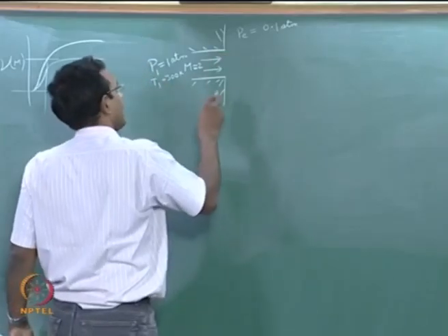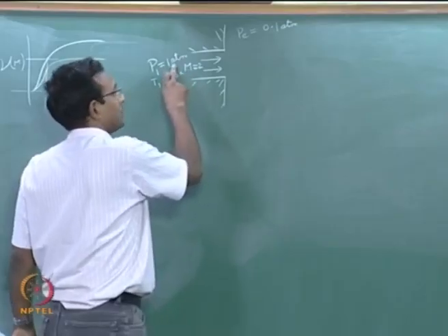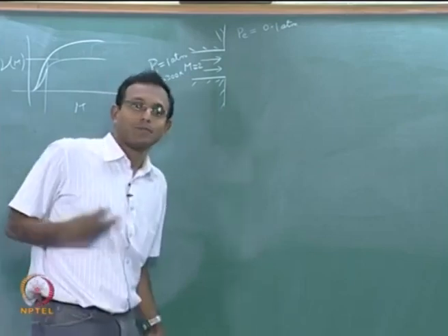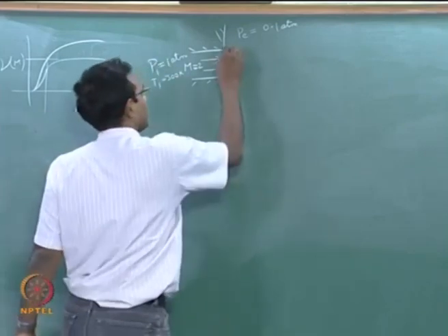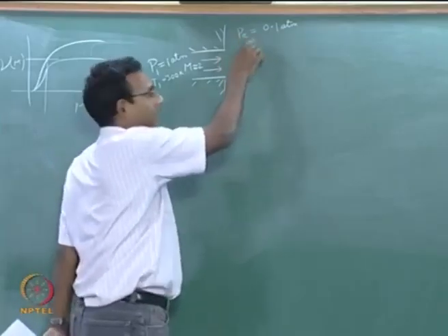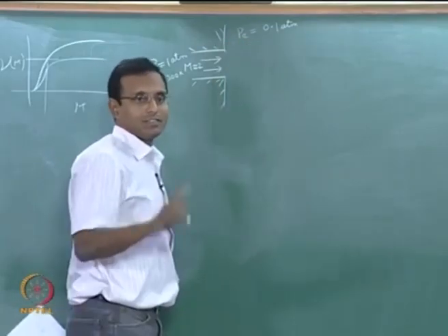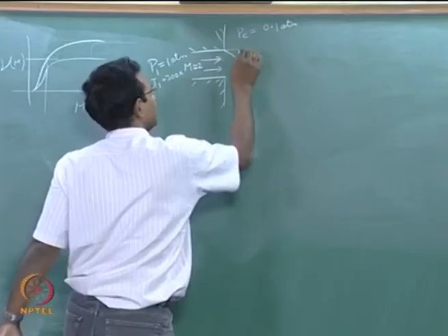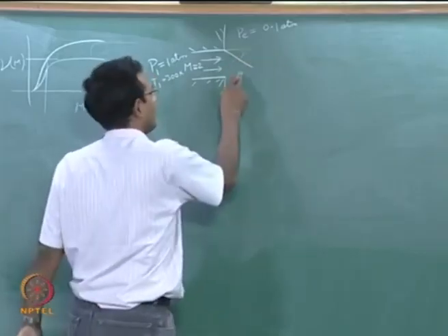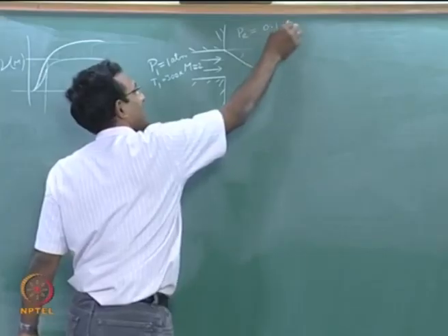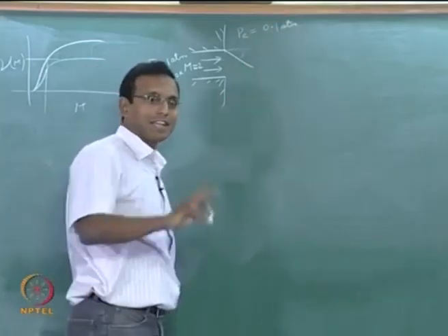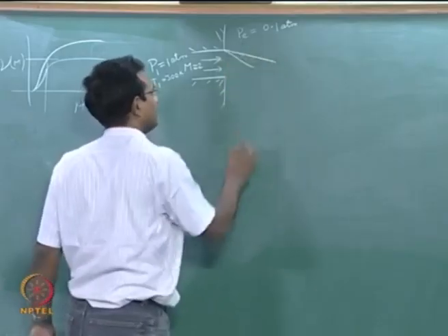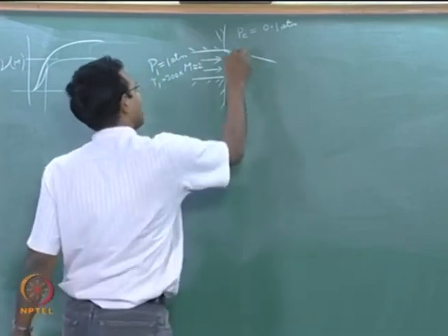Okay. Now we know that pressure is 1 atmosphere and it has to decrease to 0.1 atmosphere, which means the flow has to expand more. Okay. If it has to expand more, because this is the new boundary condition, then it has to have expansion fans. The very first fan will be with respect to this angle 30 degrees, something like this. This angle is 30 degrees. That is the first fan angle. The last one will be decided by what is the final Mach number. Let us say you can calculate all that. I will just draw some angle roughly currently. Let us assume this is correct for now. Okay. But how will I calculate this final Mach number?